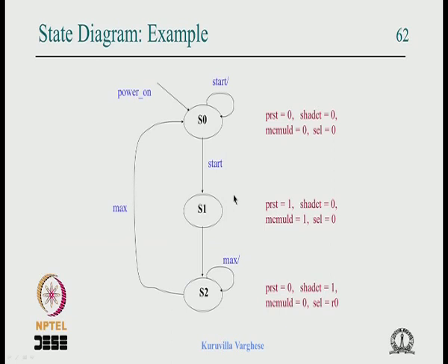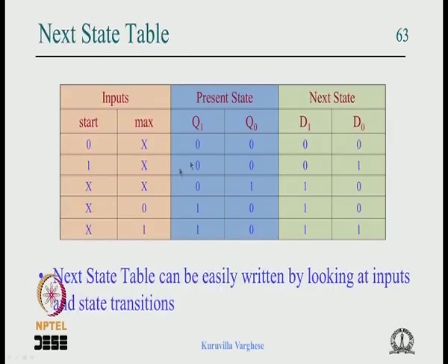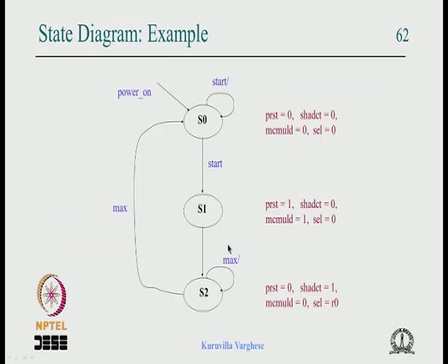So many times in design we need not write this table, we describe it in a hardware description language looking at the state diagram. The moment you design the state diagram, the controller design is over. We describe this next state logic in hardware description language, then the design is done.